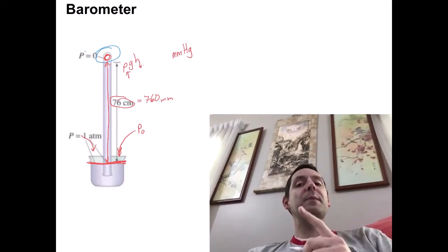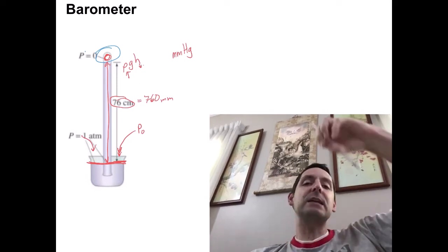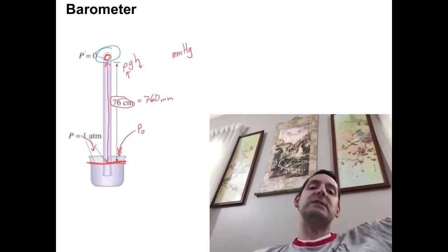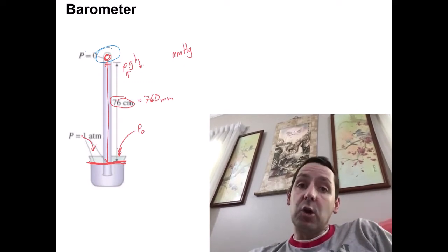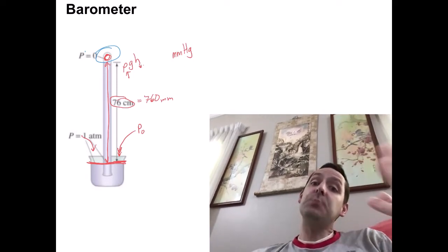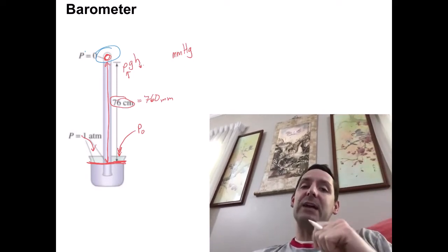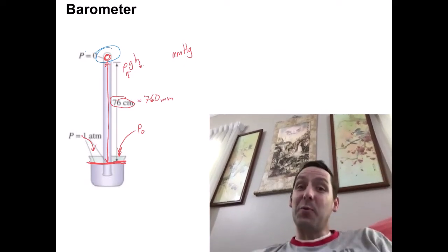Now, please do remember that science never sucks. So it's not that the fluid is getting sucked up the tube, it's that the outside pressure, which is higher, is pushing the fluid, and it's getting pushed up to that lower pressure up there. And it gets pushed up until it is actually exactly the same pressure. All right, so there's our barometer.